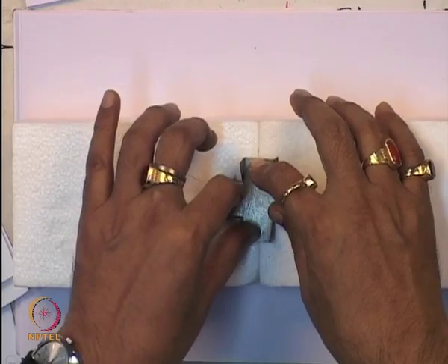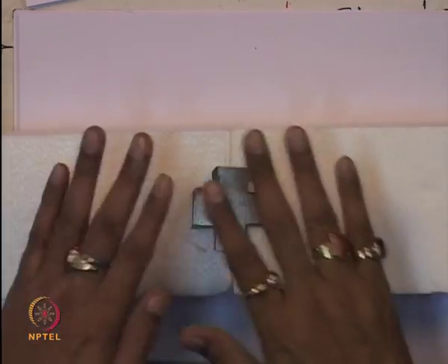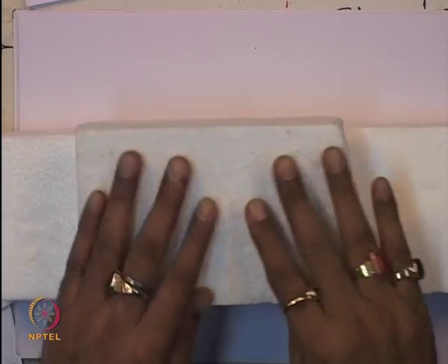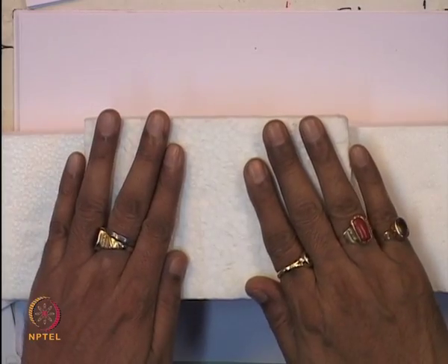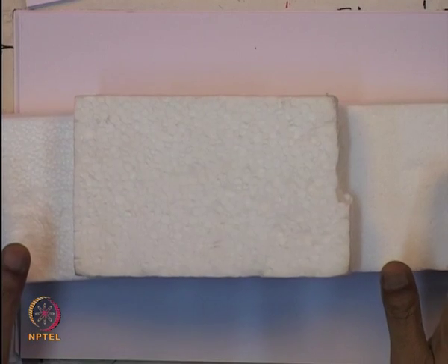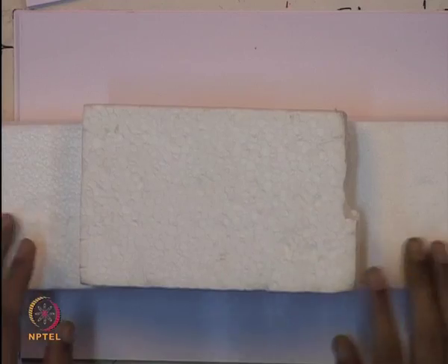So it can be jointed like this, okay, and then you can place another also, if it is required, you can place another geofoam. So that there should not be any slippage. So this geofoam block can be fixed together using this galvanized mild steel plate with sharp pointed multi-barbed connector up and down.